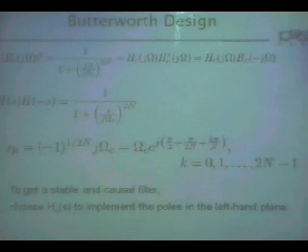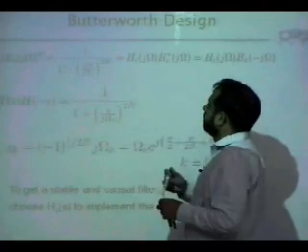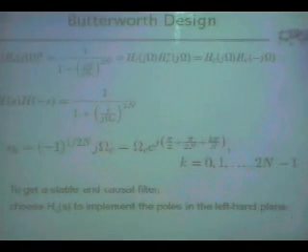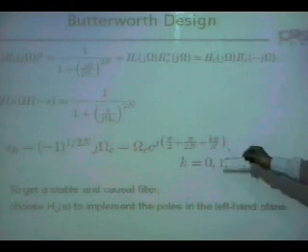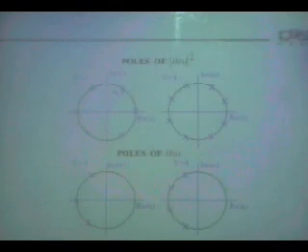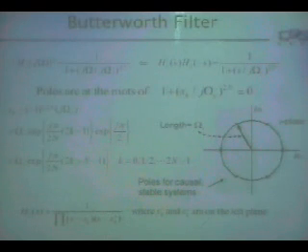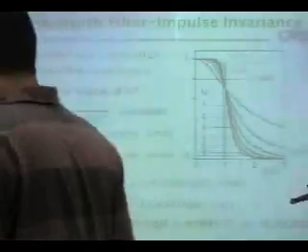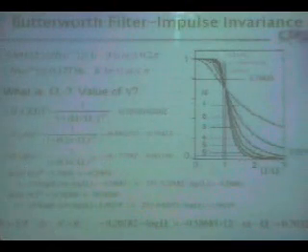So we have seen the problems with it and the mathematical relationship, and then we covered the Butterworth filter design method, where you can design a Butterworth filter using this particular expression of frequency. In this there are two design parameters, capital N and omega c, so you need 2 points. So these are the pole locations. We covered how you select the poles, and primarily we did this example, which just gives you an idea of how the filters are designed in the analog domain.